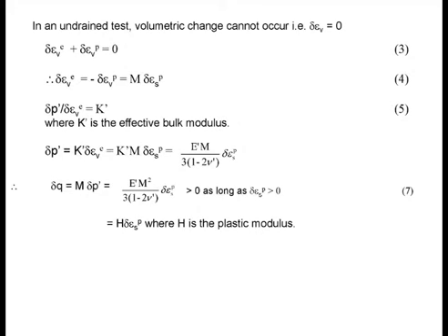Okay? So the soil developed the suction to enforce elastic compression so that at the end of the day, the total volumetric strain increment comes to 0. You understand? To balance out the plastic volumetric strain. Okay. So what does that mean? Mathematically, it means that the elastic volumetric strain increment must be the negative of the plastic volumetric strain increment.